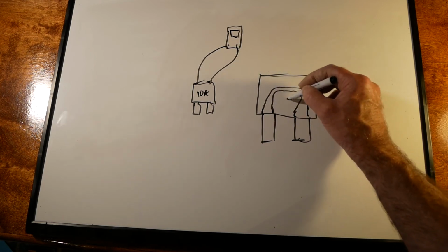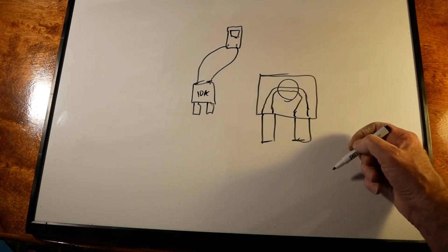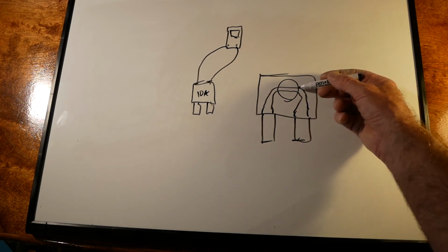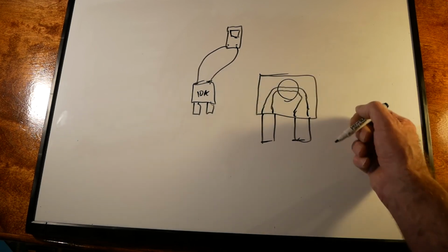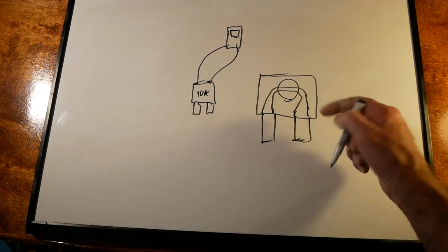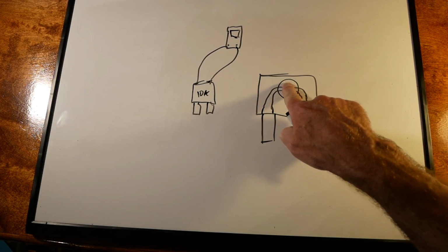And this thin part right here is calibrated to provide a certain amount of resistance. And the amount of resistance that it provides is gauged or sized to create just enough heat at a certain current flow to melt this copper. So a 10 amp fuse, when there's 10 amps flowing through this little narrow band of copper, it'll create just enough heat so that this will melt and open up.